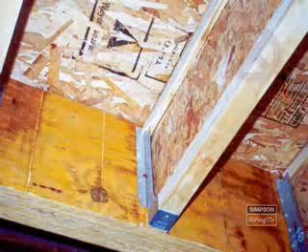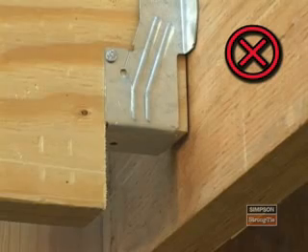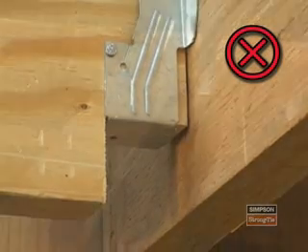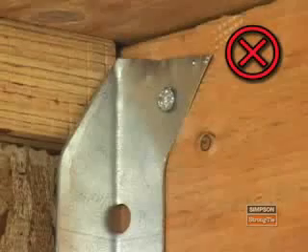Don't squeeze or pinch the top flange of an I-joist too tightly with a hanger. Don't notch the joist, beam, or header to avoid subfloor bumps unless the engineer allows it. Notching the joist, beam, or header will reduce the allowable load values of the structure. Don't cut any part of the hanger.